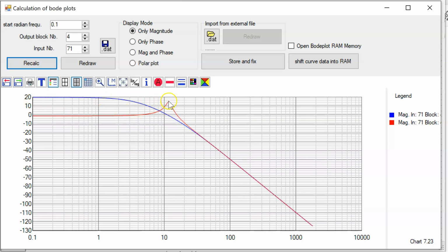That's a factor of 5. What does that mean for a closed loop system? If the input is this frequency, then you lost the control, because then the output is not equal to the input. That means 0 dB. The output has an amplitude which is 5 times larger than the input. That is not really what you want. But you can't see this real behavior with the Bode plot.